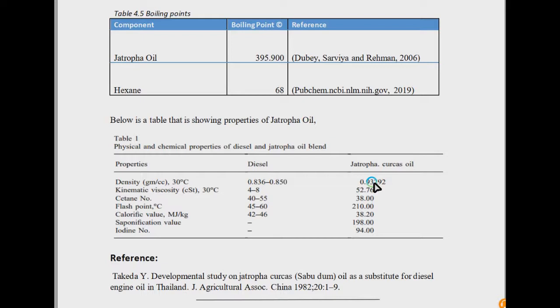the equipment or extractor. Here, the CP of Jatropha seeds is assumed to be 750 joule per kilogram Kelvin with 10% moisture. The moisture always remains on the surface of the seed. Sometimes CP of hexane is taken as 2.35 kilojoule per kilogram Kelvin, and the CP of Jatropha oil in the literature is found to be 3.5 kilojoule per kilogram Kelvin.